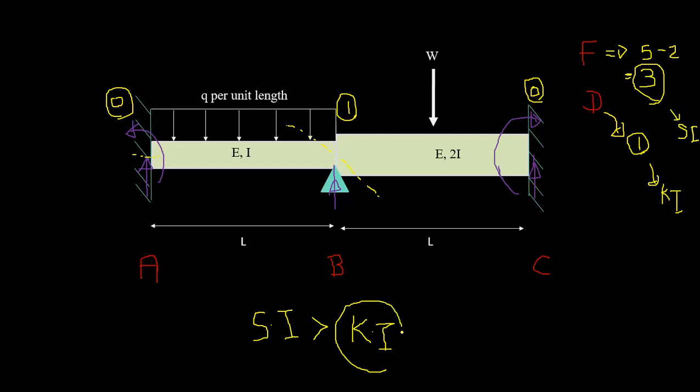So what happens is it's better to use displacement method, where you can solve it using less number of steps. So that means you are solving for this unknown displacement, right? So if you are solving for this displacement, first thing you need to do is make it 0 and make your primary structure, right? So you are solving for something, you don't know the value, let's say theta, right? So in the next slide I will write it. So how do I make it?